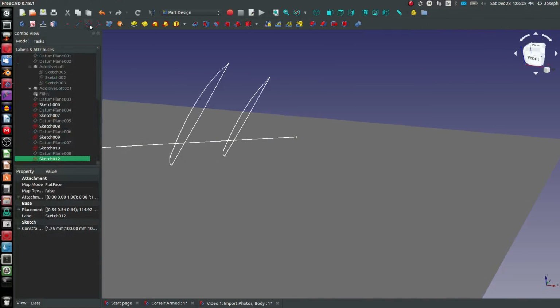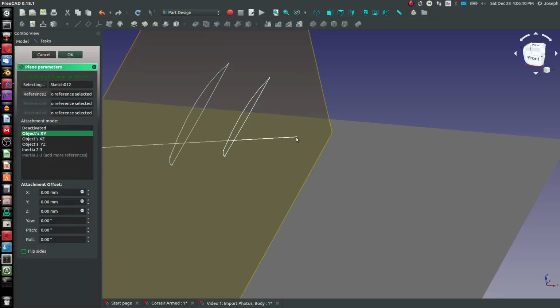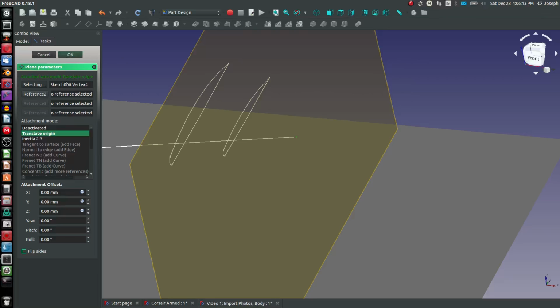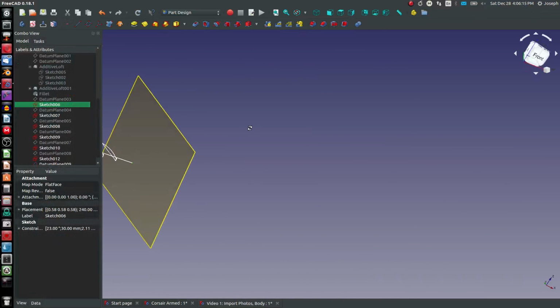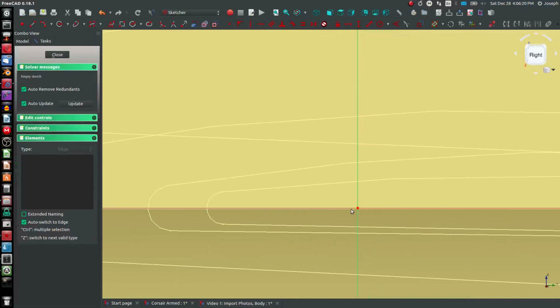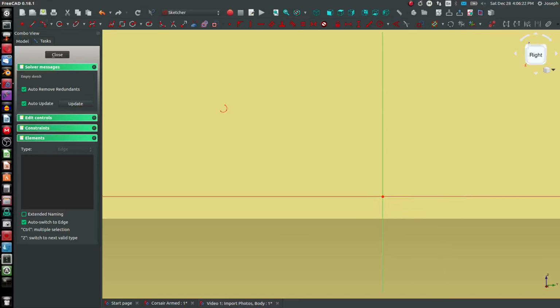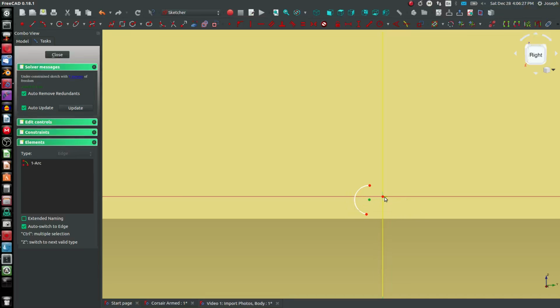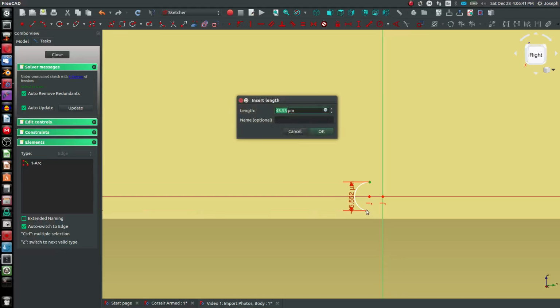Next, and this will be the last one if you're not already in Paint. Create a datum plane and put it right on that point, which is normal to the line as always. We're going to create a sketch. I'm going to create a very small profile, right? Very small. I'm going to say horizontal. Horizontal there. I'm going to go straight vertical here.